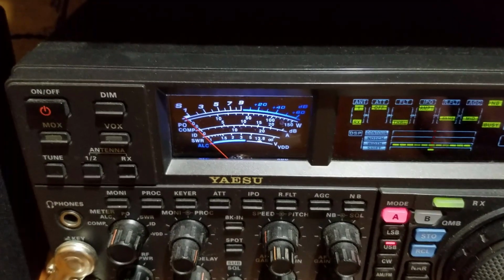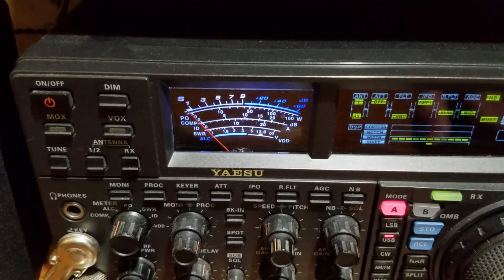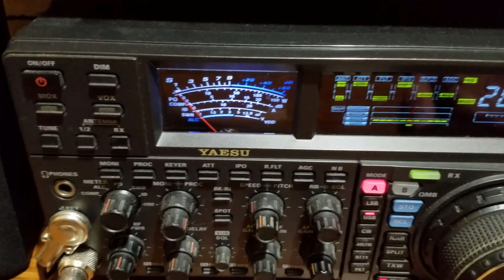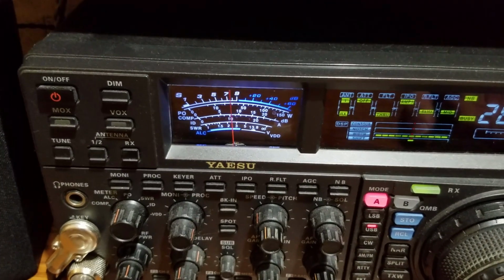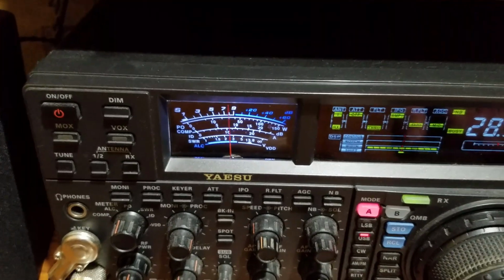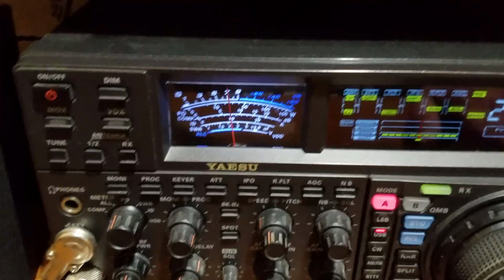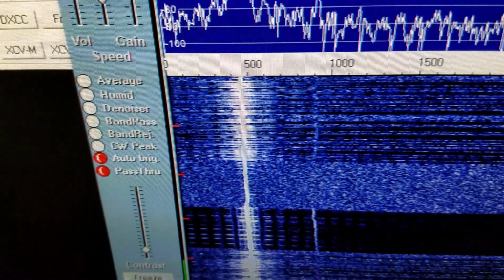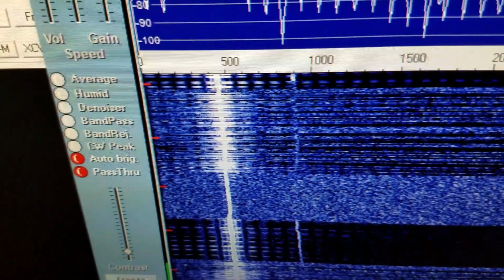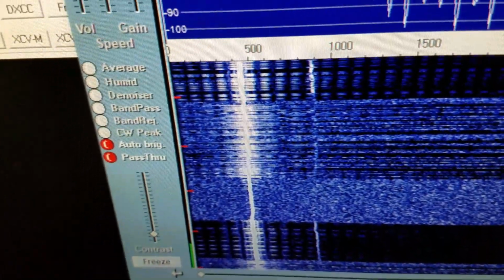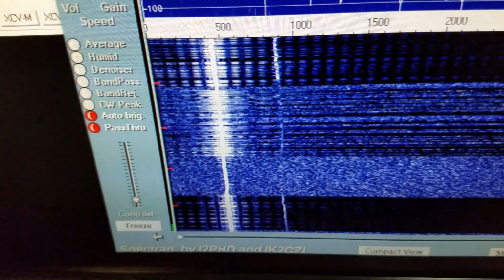So a couple of things about this. You can still hear the signal weakly when the beacon's not sending. There's enough leakage from that board, and it's just in the other room. And personally, I don't like the keying on this very much. It's a little choppy sounding to me. And also, it's clicky. You can see on the waterfall the width of the signal here with the key clicks. It's not the cleanest thing in any way.